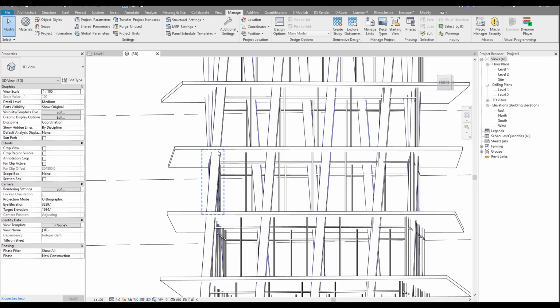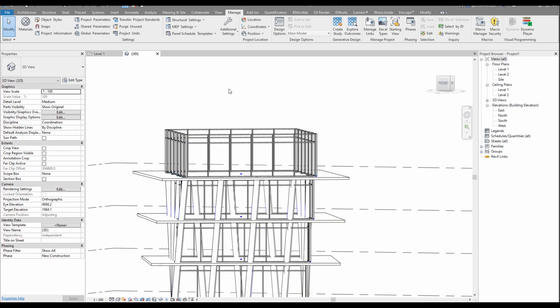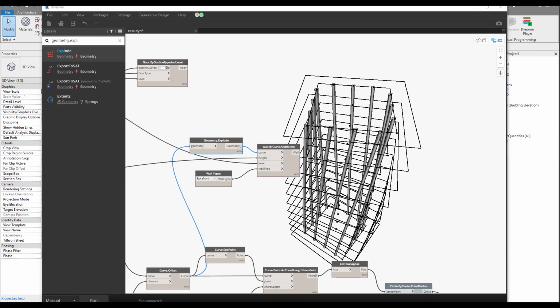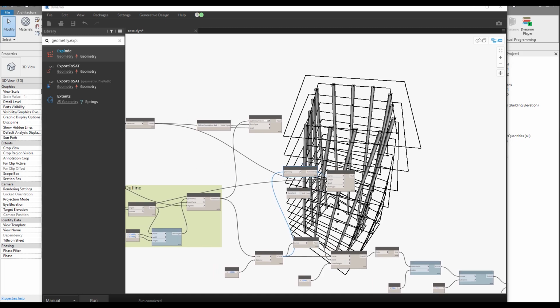First, our height is exactly from level to level, and it's going inside our floor. This is really bad. We need to make an offset from the level. We also have the last level, which we don't need. So let's change these things, and our code will be clearer. First we'll start from the level.